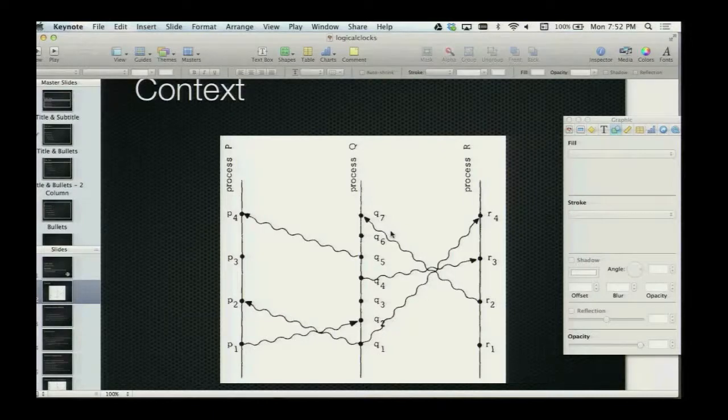I know it sounds like there's always a side effect from receiving a message. Like it's eating up DMA channel bandwidth or something, which could perturb some other timing, which would then have an effect. It just shifts other events forward in time because it's occupying some time. So really, I'm arguing that if the receipt of the message has no side effect, then something. And what you're telling me is, you'd better be incredibly careful about "has no side effect." Even timing effects can be enough for a side effect that changes the evolution of things, if other messages are arriving and the order in which they arrive is perturbed.